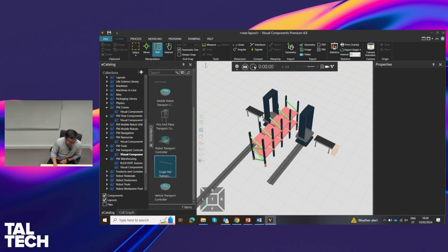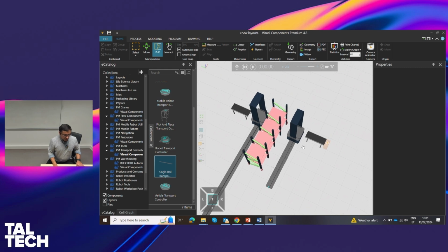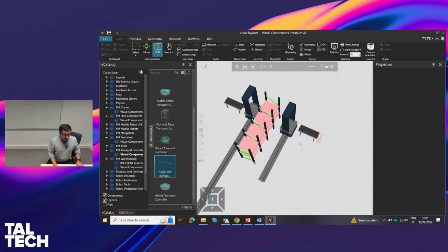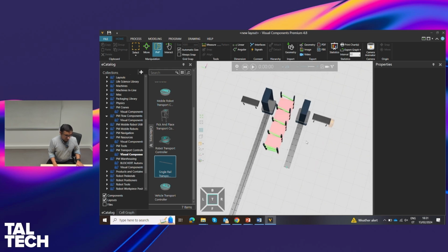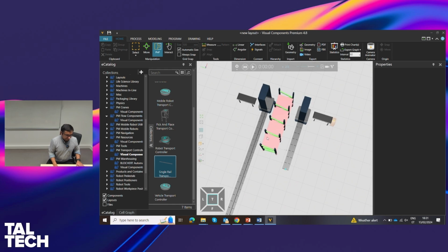So if I play the simulation, you see these parts are coming in. Anyway, nothing is working in a sense, because there is no input signal, or these process tags are missing. So we need to put those from conveyor to conveyor process components. And also we need to change the shape, but let's first try to connect the flow.